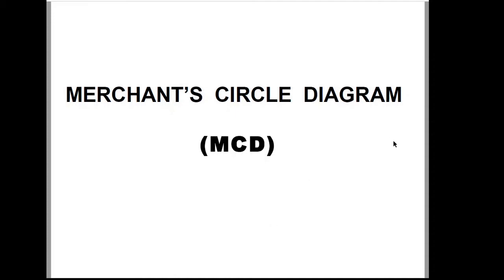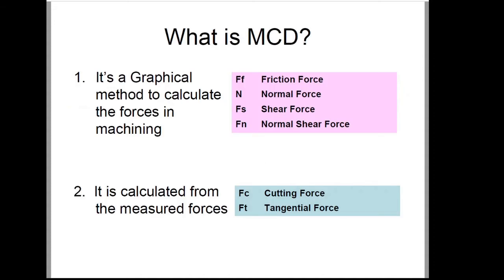Let us discuss the merchant circle diagram. Merchant circle is a graphical method to calculate the non-measurable forces acting during machining or metal cutting.